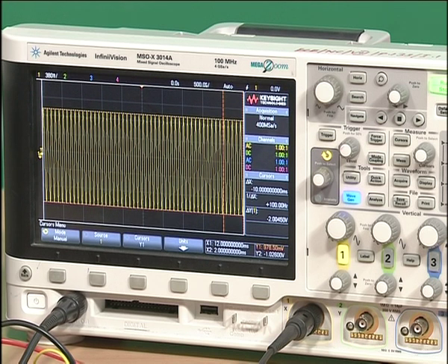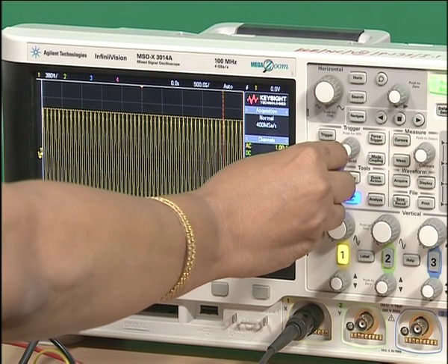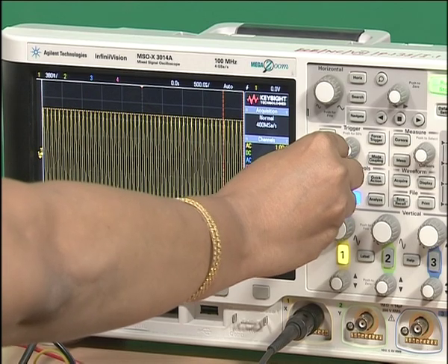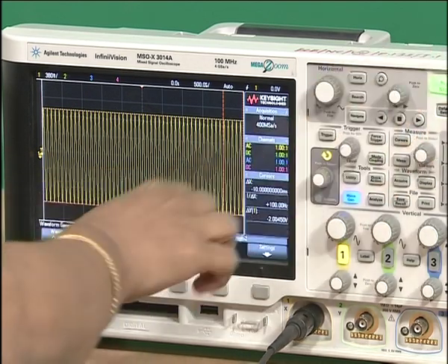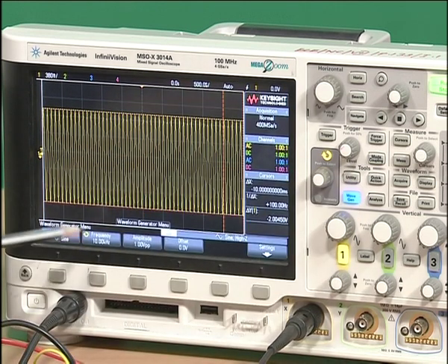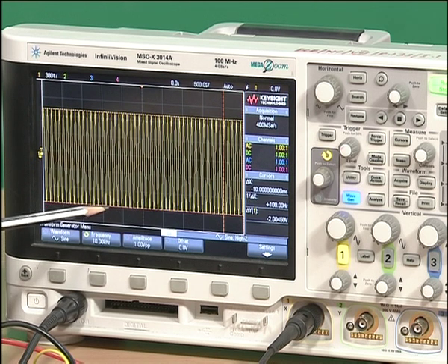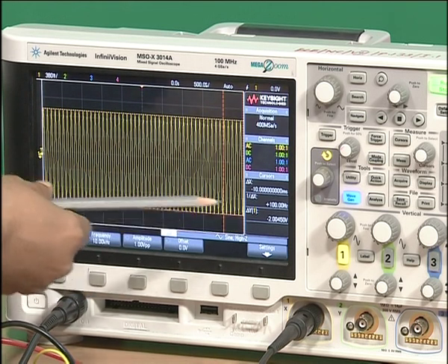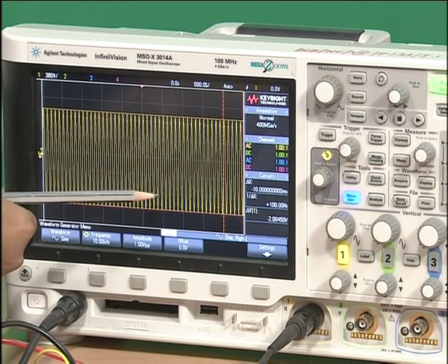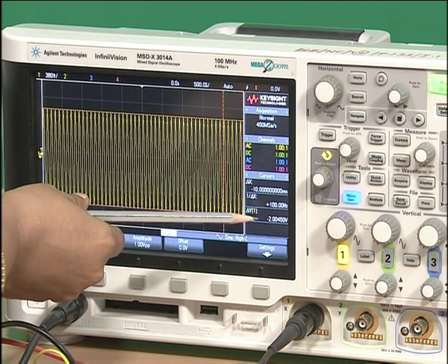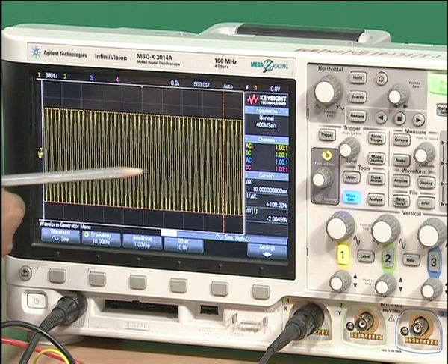Input signal set as 1 volt and the frequency can be varied and the gain in the pass band can be verified. Now, the frequency that you can see here is 10 kilohertz. So, 1 kilohertz is the cutoff frequency, so 10 kilohertz is in the pass band and the peak to peak voltage that you can see in the oscilloscope is 2 volts. So, since the input signal is 1 volt and the output voltage here is now 2 volts, the gain is now 2, which is the desired one.